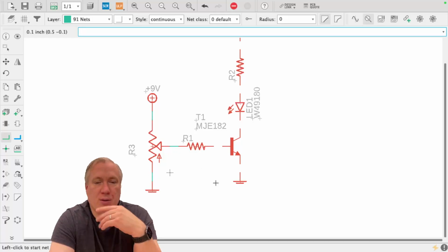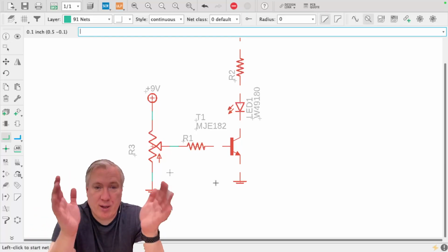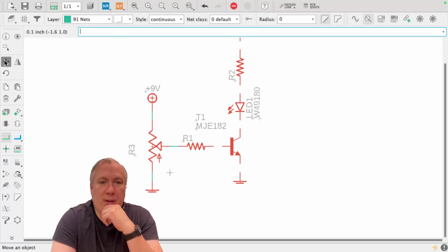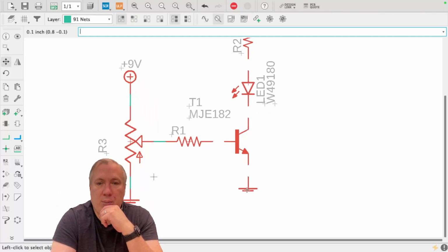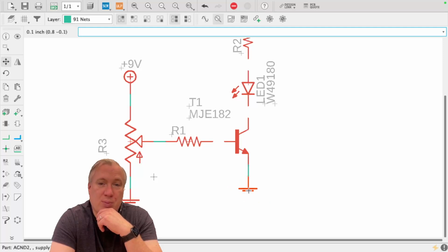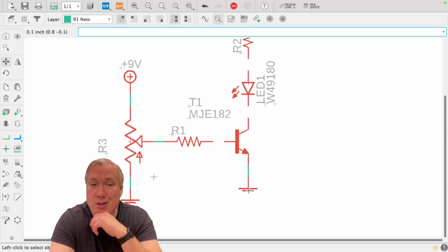Okay, so that's the tried and true method because I can see the circle and I can see another circle, and when I click them both, I'm in those circles. I know I'm connected. The other method that can be used is you can place a part next to another part, and usually it will automatically connect it. But I say usually because there's plenty of scenarios in which it hasn't happened and it looks connected, or you think you put them together, but you actually did something like this.